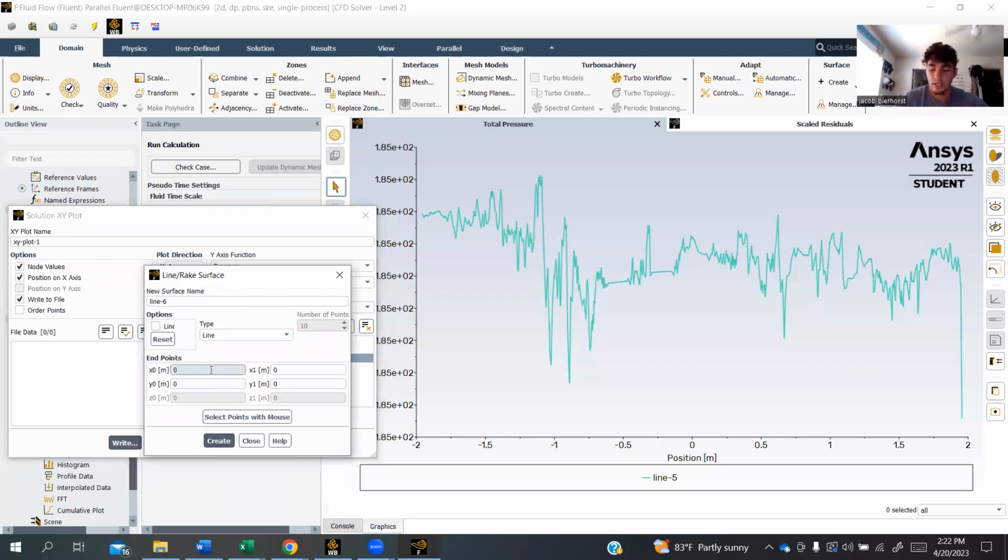Okay. So now we are going to need a new line. Okay. And your center of your test section is at 1.9558. Okay. And we have to go to the center now of your test section. So I would add the first part plus the length of the test section divided by 2, which is about 1.72 meters. Find the difference between your natural center and the center of the test section. It's about 0.2286 meters. Okay. And now if your center point of 1.9 is 0, then your x point of the center would be negative 0.2286. Okay.